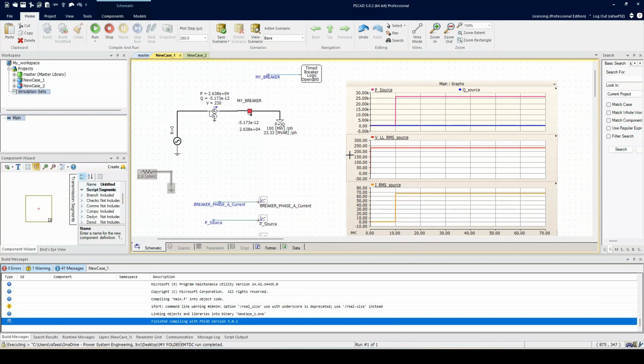So it's finished compiling already. One more note at the bottom right here: when you see these gears moving, that means it's doing something. Sometimes you notice that it's not doing anything, but if these gears are moving, that means PSCAD is still running. And this right here, 760-585, is your cursor location on the canvas, and it gets very interesting.